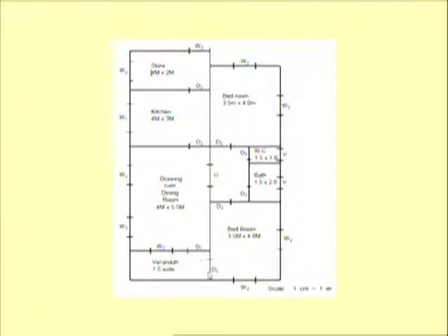The doors having the same size are shown, this D2, all these D2s are having the same size. Similarly, this D3 is provided at the WC and bath, they are having a lesser size. Similarly, all these windows are having the W2 size, that means all these windows are having the same size. The scale is written here, 1 centimeter equal to 1 meter.